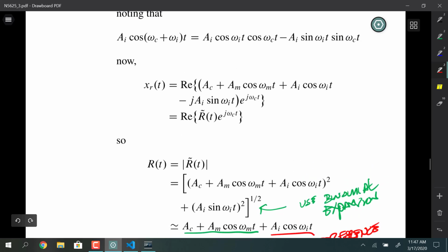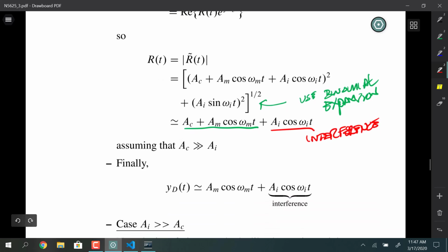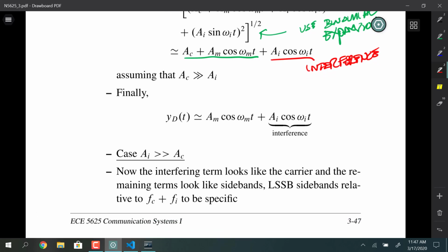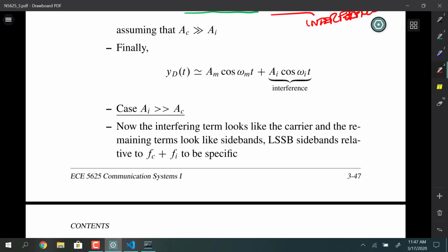It's acceptable. We just have to mitigate it in the same way we did for the coherent demodulator. So once we put the DC block in there to remove the pure carrier from our envelope detector, we're fine.